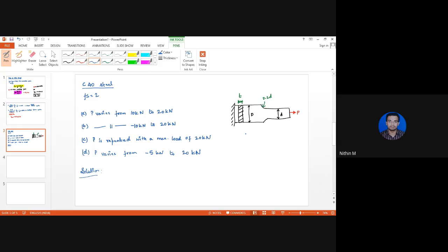If there are any changes in the cross sectional area of the component, then the component will be subjected to stress concentration. The same is the case here. This component has a reduction in the width of the plate. Thereby, there is an effect of stress concentration factor which is present. So we will be making use of the modified Soderberg equation.